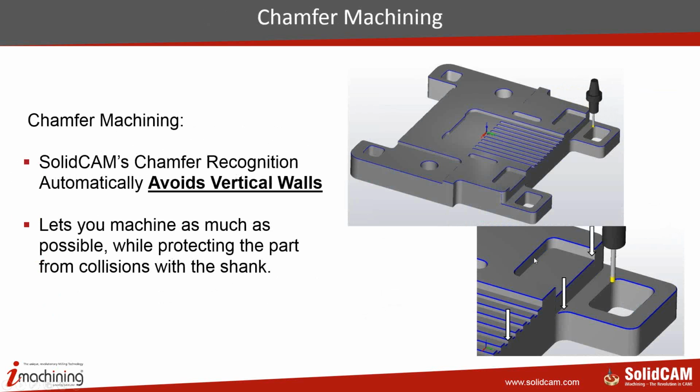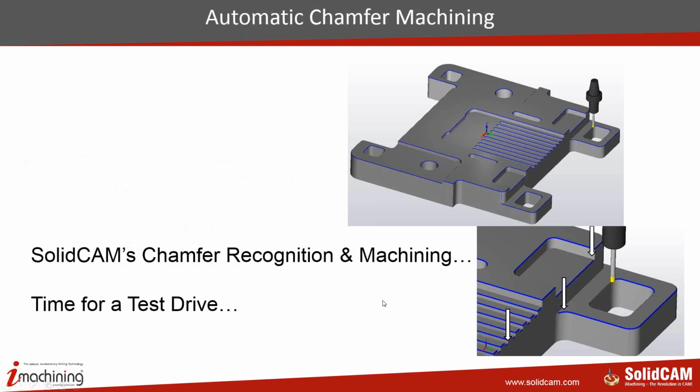If you'll note in these corners over here, we have a wall. The safety offset automatically controls that the tool will not come close to that wall itself, thereby gouging that wall. It'll actually prevent gouging from areas such as this, areas such as this over here. You can see all of these areas over here is prevented by this option for safety distance from the wall itself. Let's see exactly now how this works.